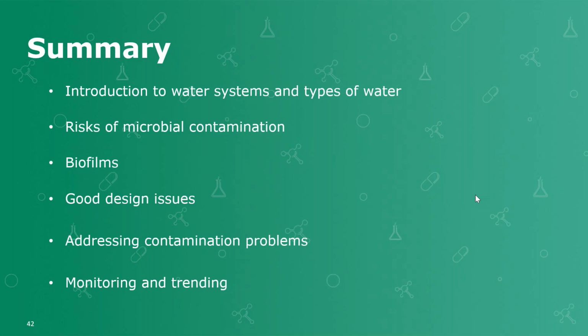If we get biofilm formation in a water system, it exacerbates the contamination risk, and that can lead to anything from slowly introducing contamination to increasing the corrosion rate of pipes, and, for non-sterile pharmaceuticals, to a predominance of pathogens of concern. So we looked at Pseudomonas aeruginosa and the Burkholderia cepacia complex. This also means that microbial control is a matter of concern not just for microbiologists, but also for engineers and the users of the water, the production personnel.